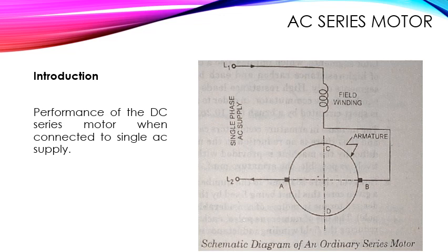There is another adverse effect of the high inductance of the shunt field. The high inductance of the shunt field causes the field current, and therefore the flux, to lag nearly 90° in time with respect to the line voltage.